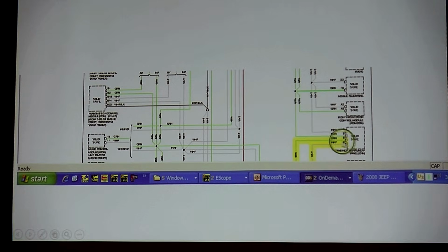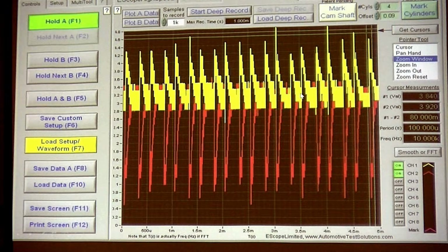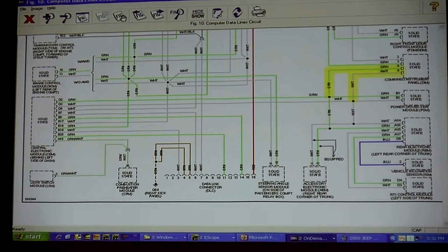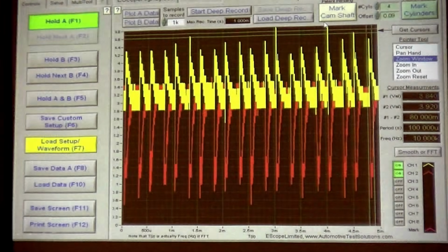If I unplug that, I open the circuit to all these. If I open that circuit, what's going to happen? It rings. You made it ring. You unplugged it and you took the termination out, because the termination is where? It's up here. And if you look back over here, do you see how these wires come in and I have these modules down here connected? And they come up over here, and if I unplug that, I have these ring, but I took my termination apart from up here. Guys, you can't do this, okay? So you've got to bridge these.